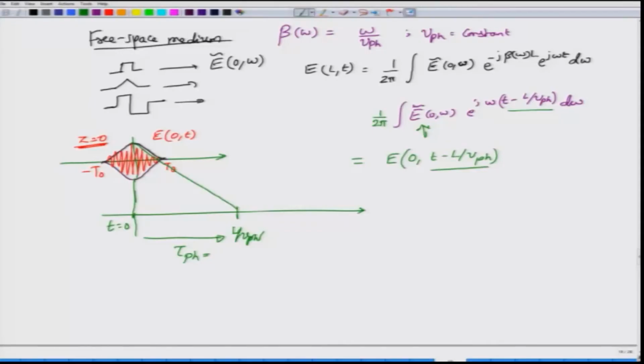That is, the entire pulse would arrive without any change in the shape. All frequency components arrive at the same time, and when you put the frequency components together and then form the inverse Fourier transform, you would see that the output would remain the same as it was at the input, no distortion. Although I might not show it correctly, there is absolutely no distortion, and the pulse would remain without any change in the pulse spectrum. So, no change is an important condition.